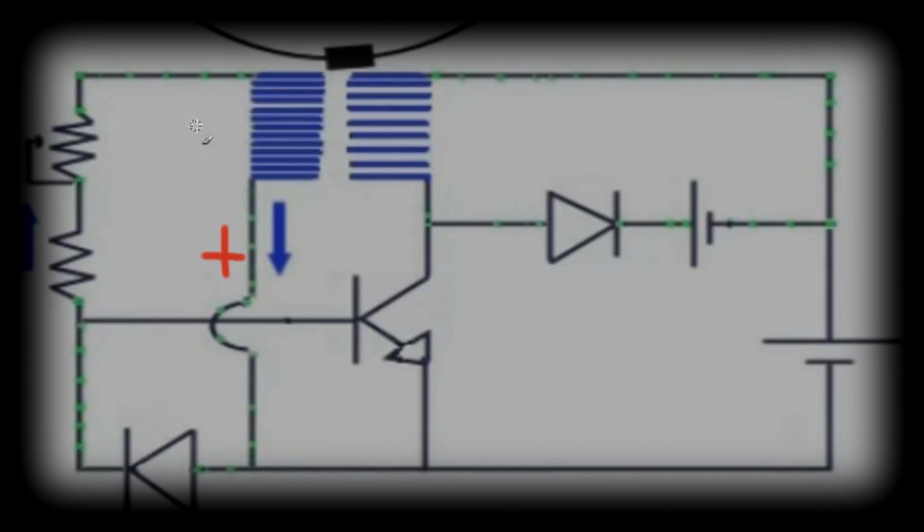If you remove all the resistance on the trigger winding here down to 0, this 100 ohms will stay in effect and allow maximum of 120 milliamps. You can drop from there by increasing the resistance on your potentiometer. And you can go from 120 milliamps down to whatever, maybe 5 milliamps.